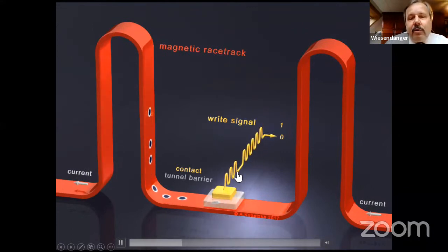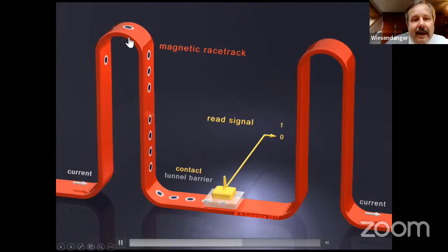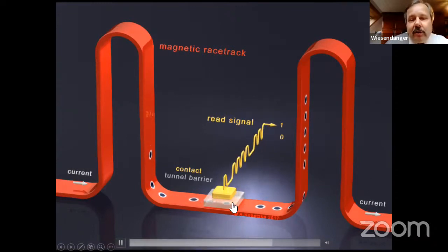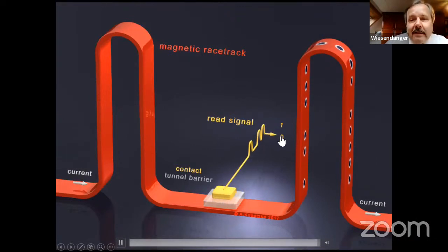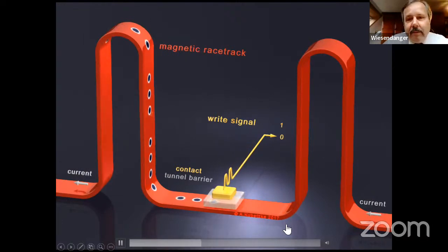electrical signals. We could create then electrical induced skyrmions in a magnetic storage layer. And then, of course, we can reverse the current flow to be able to read back basically the information of the skyrmions in this storage layer fully electrically. So this is an all electric field-based Skyrmion racetrack device, which we have proposed 5 years ago in a framework of a European project related with applications and industrial use of Skyrmion-based systems.